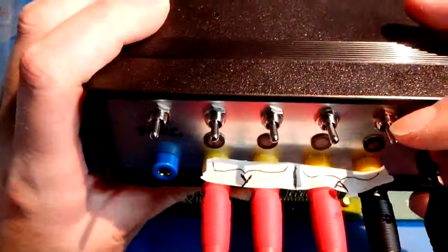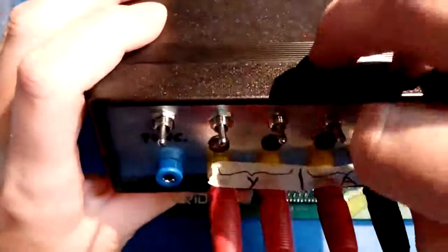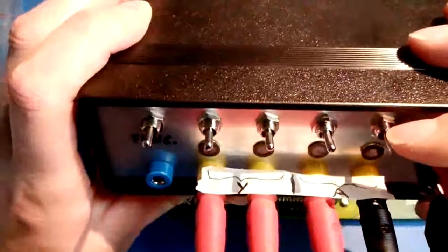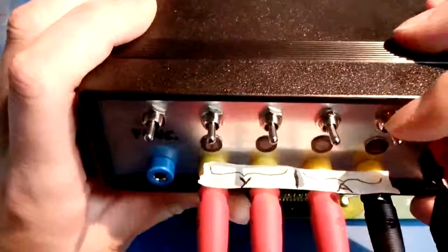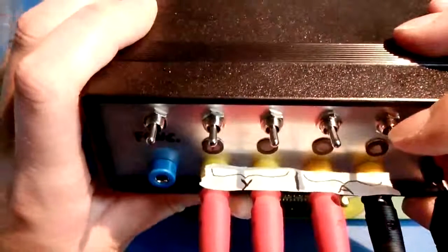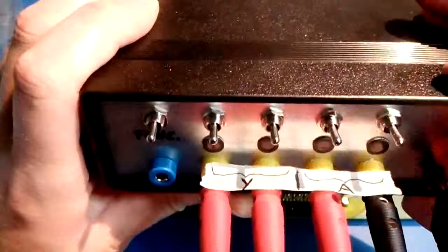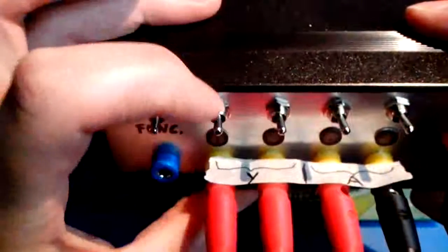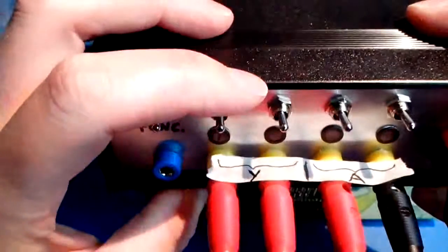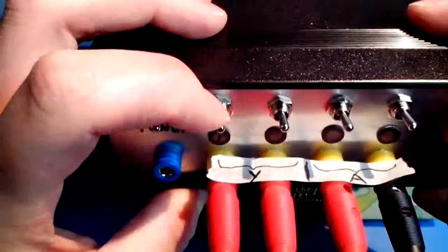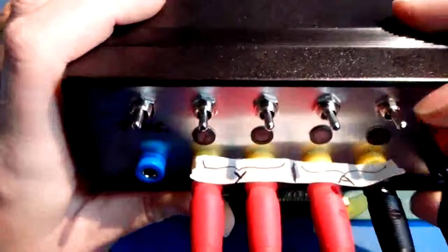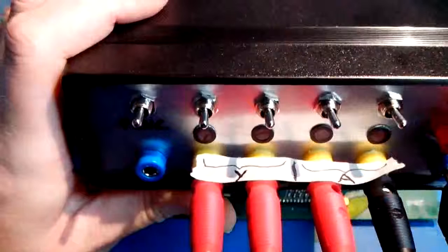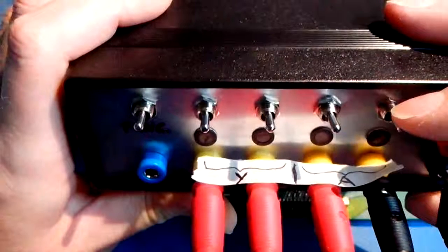So the rightmost 2 bits are 2 bits of input A. So the first 2 bits of the module, basically. The rightmost bit is the least significant bit. That is bit number 1, that is bit number 0 of the input. And likewise, the 2 leftmost LEDs and 2 leftmost switches, but we don't use them now, are the least significant bit and bit 1 of the output. And this is the case where carry in of the whole module is 0.